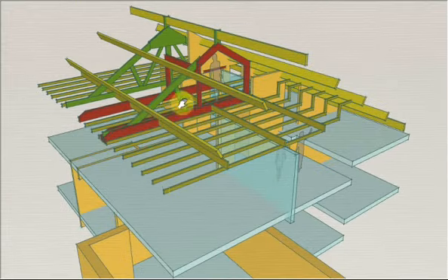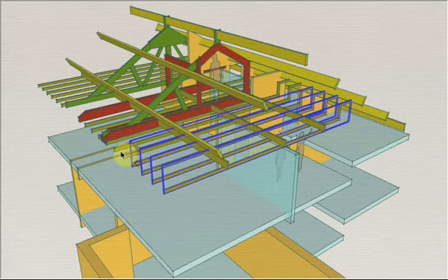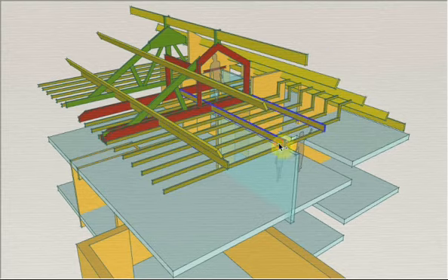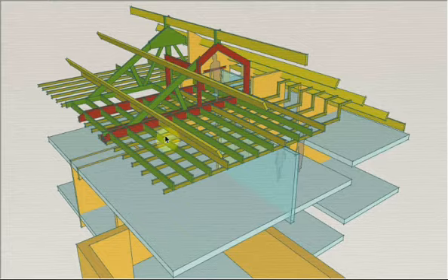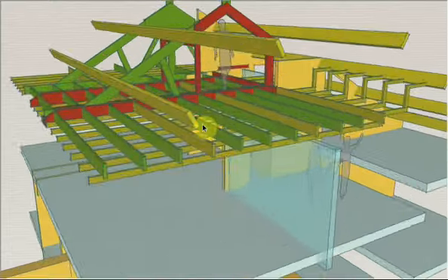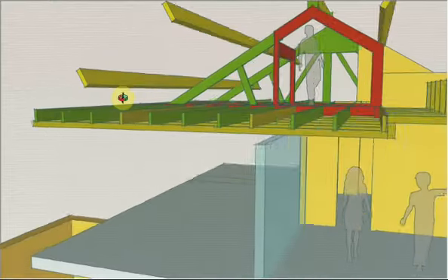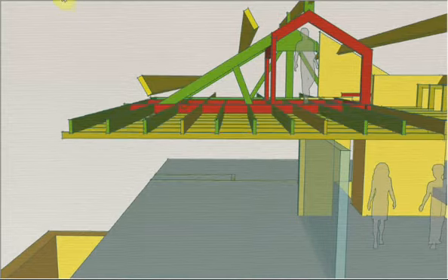There's the existing ceiling joists here, which are actually hung from these larger joists here. And what we're proposing to do is to retain all of that structure so the ceiling doesn't have to come down to cause further disruption. So to do that, we're proposing to put timbers in between, new timbers in between, like so.